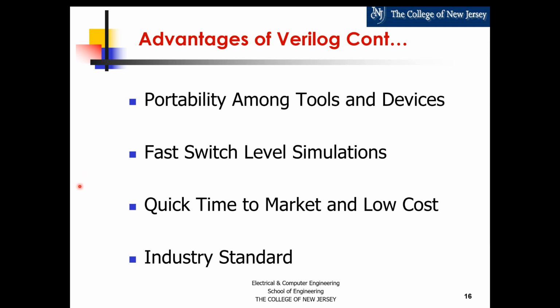And as you'll see later, we call that event-driven simulation versus a time mathematical type of model and simulation like a SPICE, where you are constantly, with a small time step, evaluating sort of a Newton-Raphson type numerical analysis technique to solving the system of differential equations.